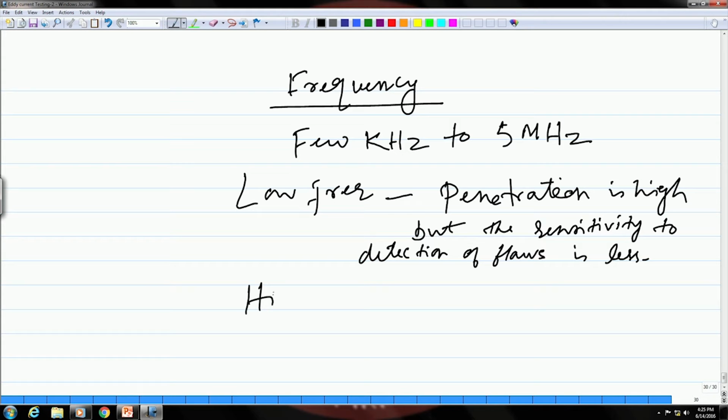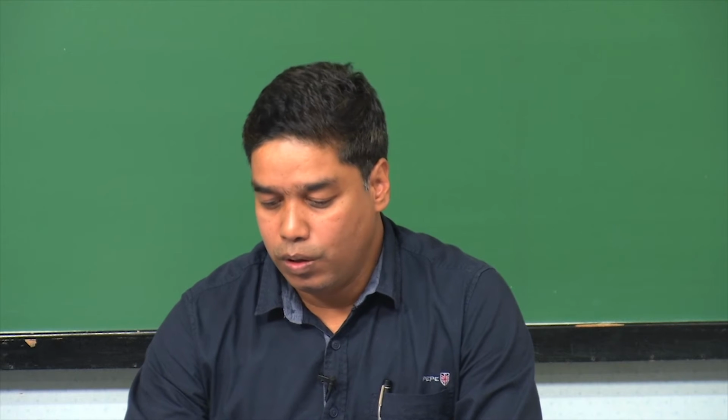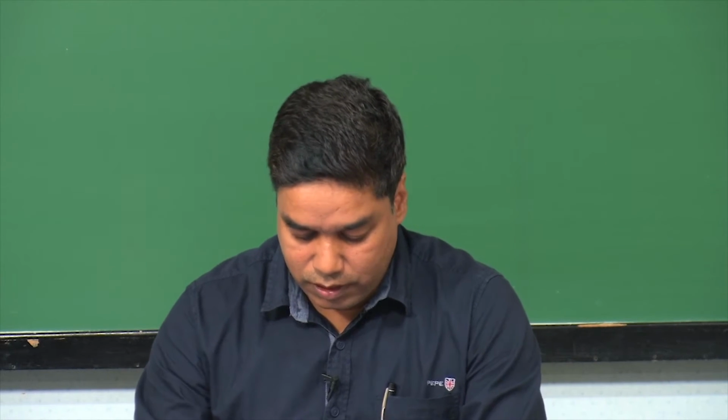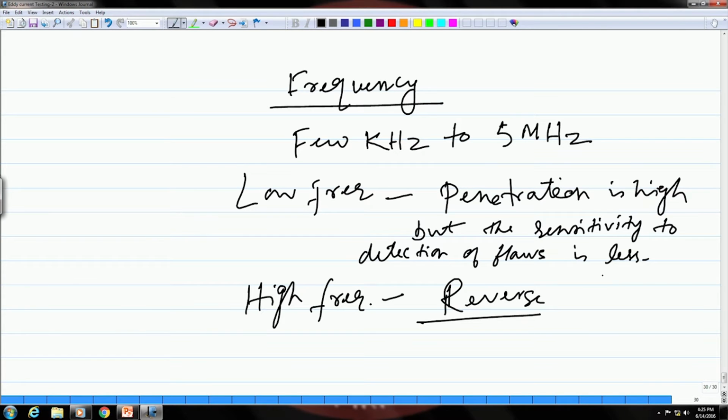And with high frequency, it is just the opposite, the reverse scenario. That means the depth of penetration would be low, but the sensitivity would be high. So, this is the effect of frequency in terms of the penetration depth and the detection of flaws.